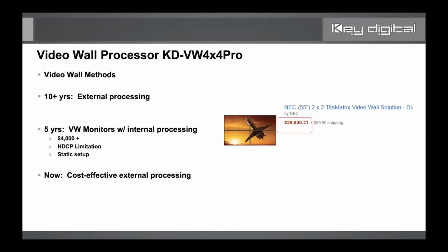And it used a special DVI adapter HDMI cable to do the video wall processing. And you had to label each display 1 to 1.5, be wired specifically. The first unit had to have special programming software in it for it to control everybody else. It probably took a week and a half and tech support to get it actually up and running. And I don't even know if it ever worked 100%.